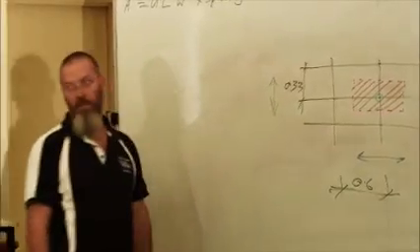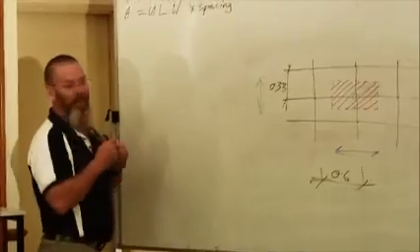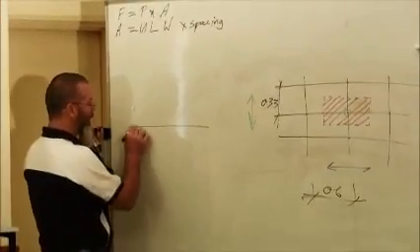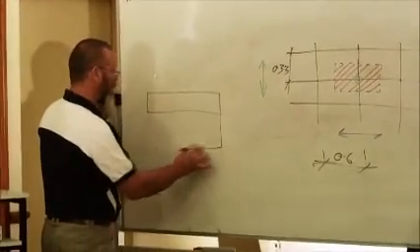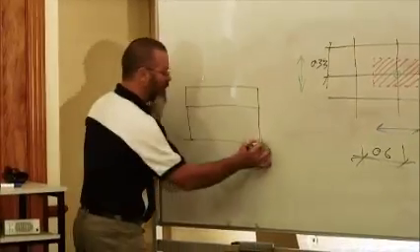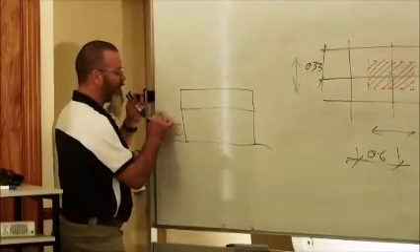Is that the same when it gets closer to the edge? No. And this is the confusing part. That's why I went back before. You've got to get out of your head the idea that this is an edge. It's not an edge. It's all connections within 1.2 metres of the fascia, barge, hip or ridge. Let me just explain that a little bit more. Here's a gable end roof. Okay? Ground, ground. This is why a gable is an edge.